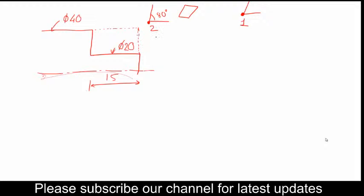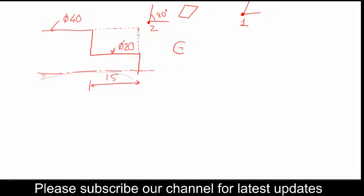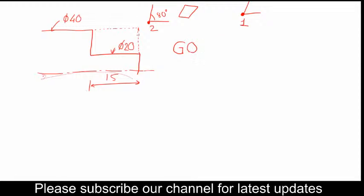Okay. So if I write G0 X45 Z2, what does it mean? The tool is currently at any position, which can be 1, but I need the tool to be at X45. From this point, this distance would be 45 in diameter. So half of it should be above and half should be below. It should be 45 by 2, but we write the X coordinate in diameter. Okay, so it will be X45.